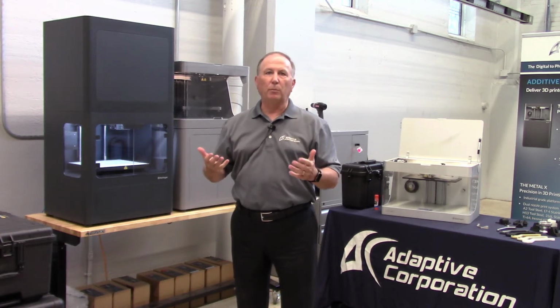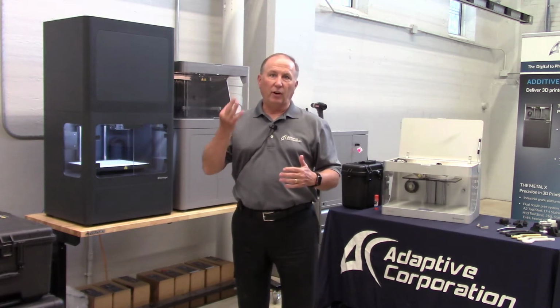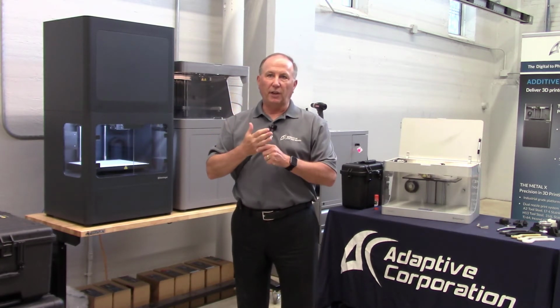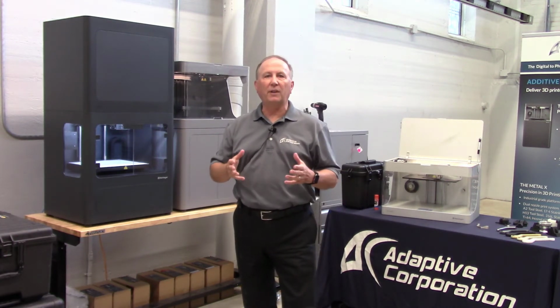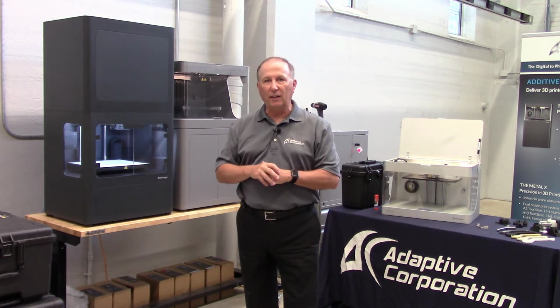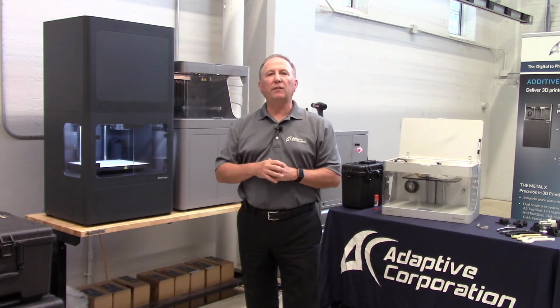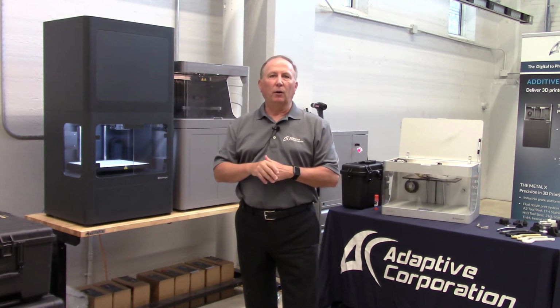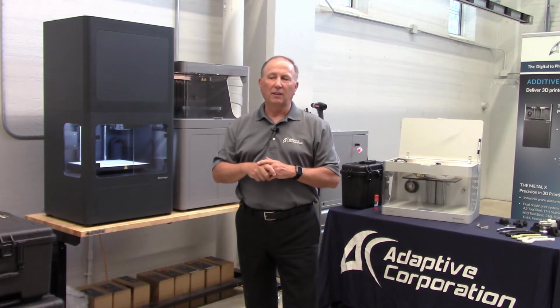The process that we employ in metal 3D printing involves really 3 steps. Step 1 is that we print the part into, generically we'll call it a green state. The process that we have encapsulated in 3D printing technology in the past came out of the castings industry. A lot of people knew it as MIM, M-I-M, which is the metal injection molding process.